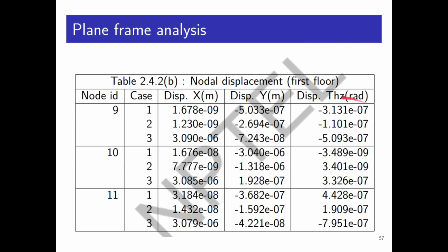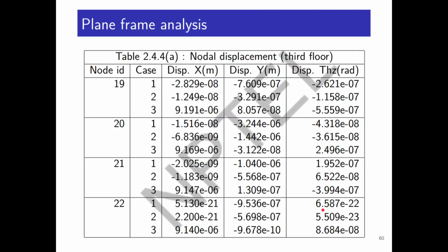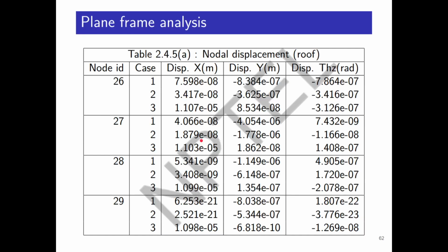Similarly in the case of displacement, displacement does not mean only deflection, it can also mean rotation in finite element. So always be clear with that. This is not delta, it is theta, but these are delta. All are called displacements. You have to check the unit to find whether it is deflection or rotation. These are the values generated for each floor, and the higher you go, the larger the value.